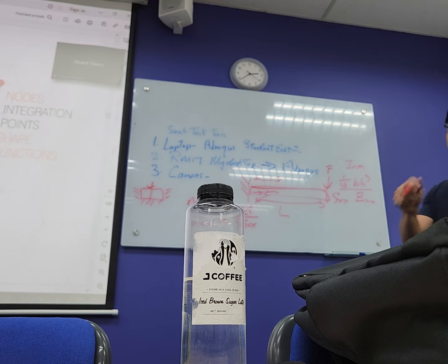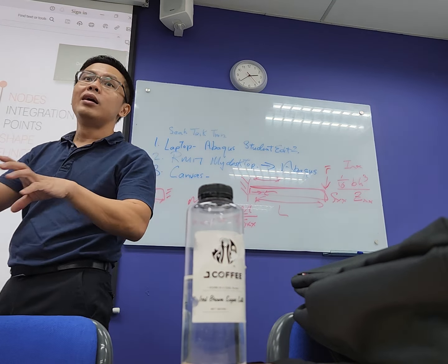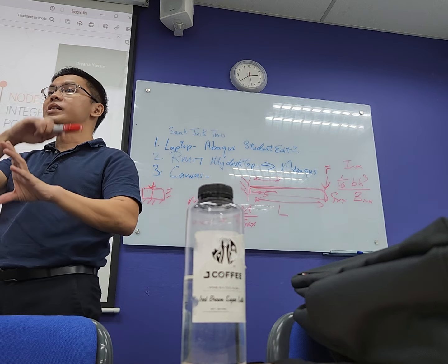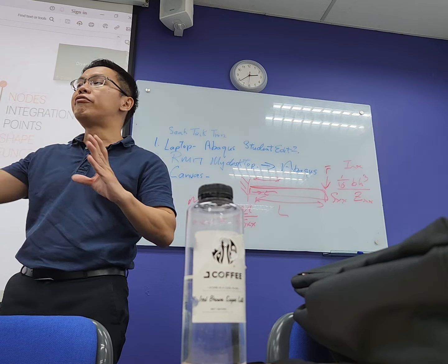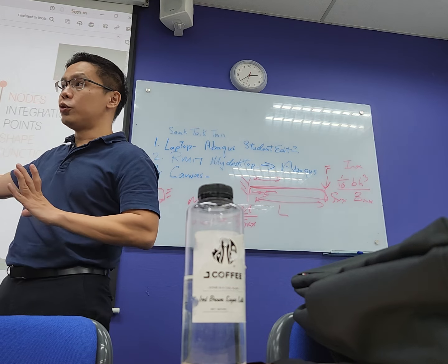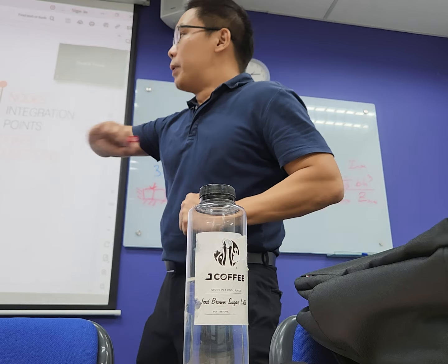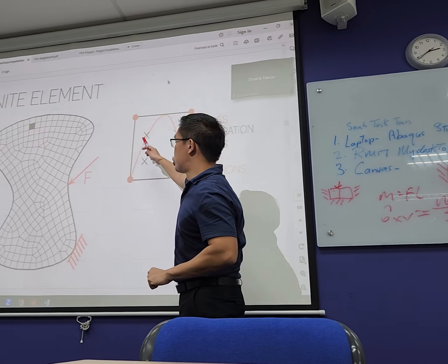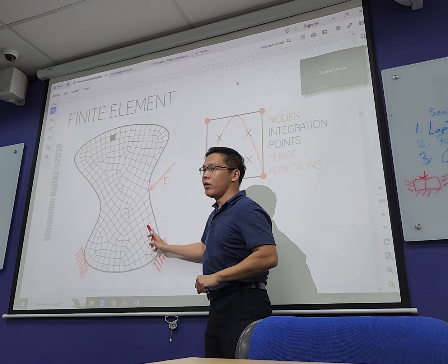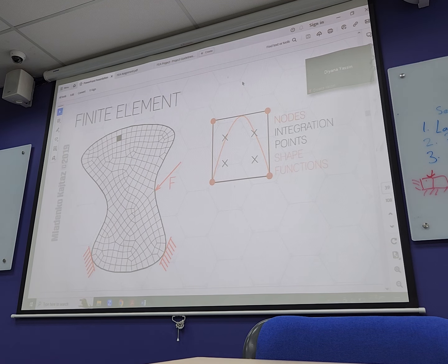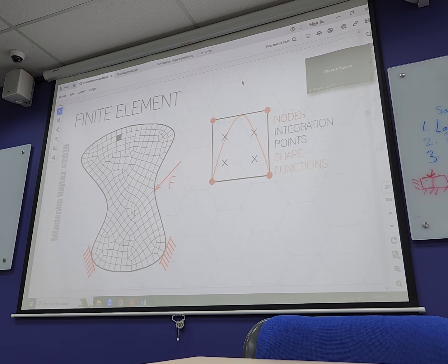And in finite element, why do I say just now that the model you use, the engine you use, is always the same? It's always the same model. You put in different governing equations, which I'm going into a little bit. But the model is the same. The model is what? The model is a shape function. That means every one of these cubes, or the square in 2D, cube in 3D format, will have the same shape function.